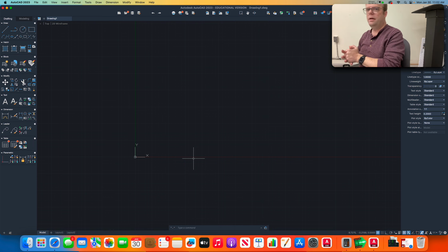And that's something that AutoCAD has pretty much stuck with. They're like, yeah, we're not drawing in scale. You are drawing the full size and the actual size of this thing. The only time you start worrying about scale is when you have to start printing it on a piece of paper. At that point, you have to think about, okay, when I'm going to print it out of a printer and put it on a piece of paper, I have to shrink this down. But until then, you really don't have to worry about it. You draw everything in full scale.